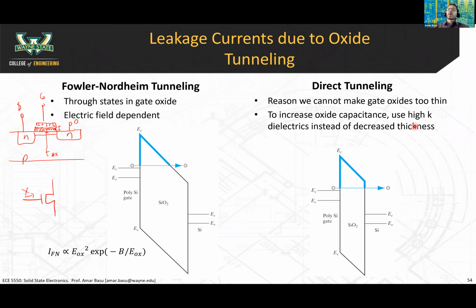So that standard model of miniaturizing the transistor, where you just decrease the thickness of the oxide, they stopped doing that, and they used a thicker oxide, but then they switched to a higher-K dielectric, meaning a dielectric with a higher dielectric constant, so that you could still maintain that constant electric field that we talked about earlier. Okay, it's a little trick that they used. Instead of decreasing the thickness of the oxide to maintain constant electric field, they just increased the dielectric constant.